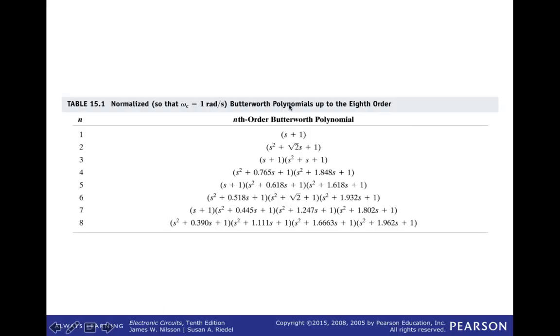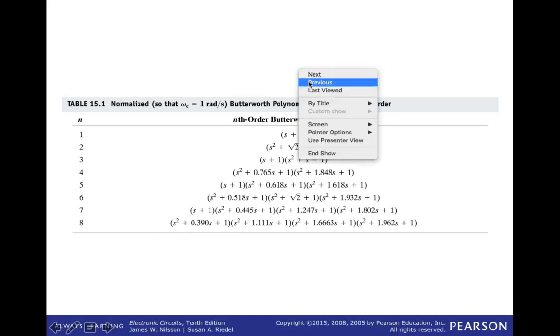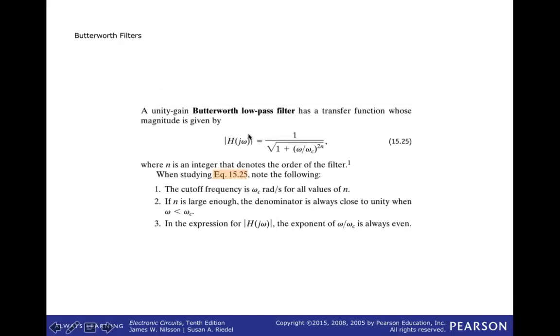Okay, now how do we get from there to here? Well, if you notice, this transfer function is in terms of j omega. And then remember that s is equal to sigma plus j omega. We let s go to j omega, we get rid of the sigma, and then we take its magnitude. And in taking the magnitude, we basically are doing an operation that makes it difficult to go backwards from j omega back to s, but that's exactly what we want to do.